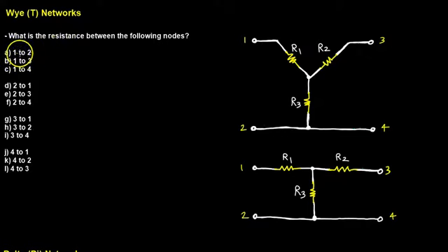Let's find the resistance between terminals 1 and 2. So let's look at 1 and 2 here. How do I find resistance? I apply some voltage across those particular terminals. It doesn't really matter what orientation it is, so long as the elements are purely passive or resistive. So I'm going to apply this V test. It could be anything. It could be 1 volt, 10 volts, according to the ratings of the resistors. We have to calculate that at some point to make sure we don't blow anything up. So we'll apply this and we'll get some I test.